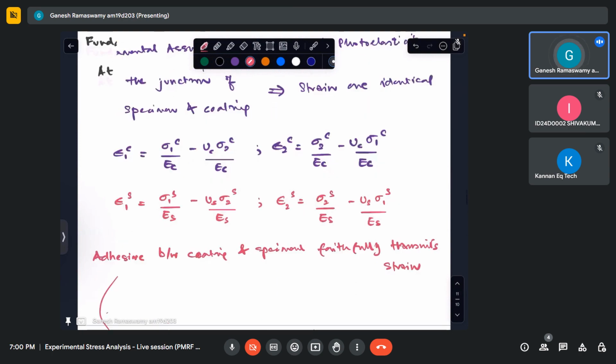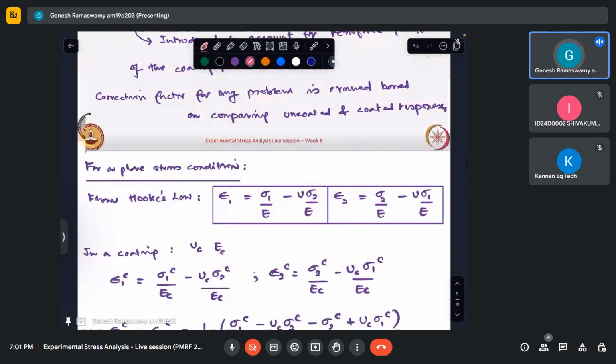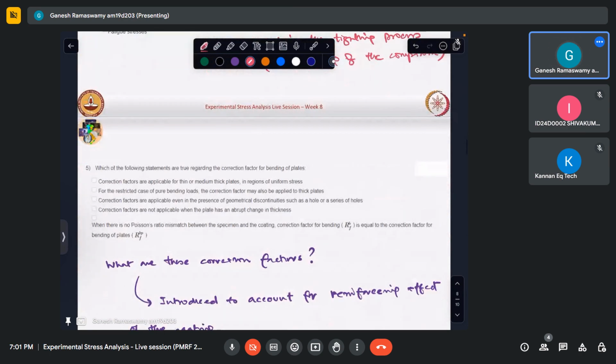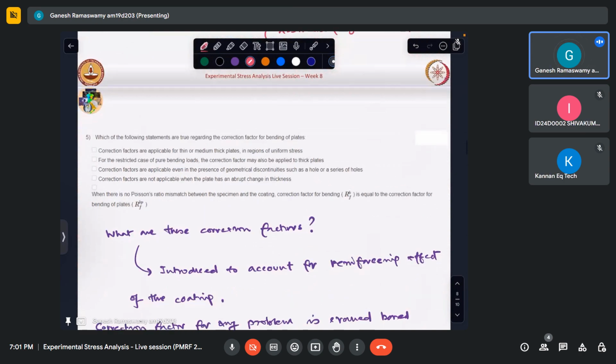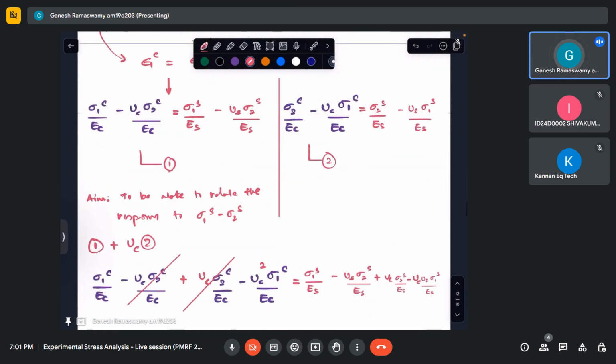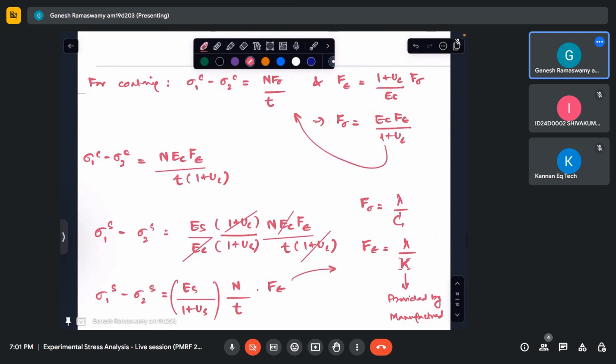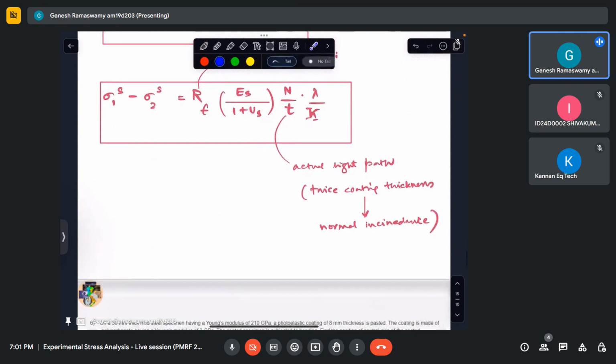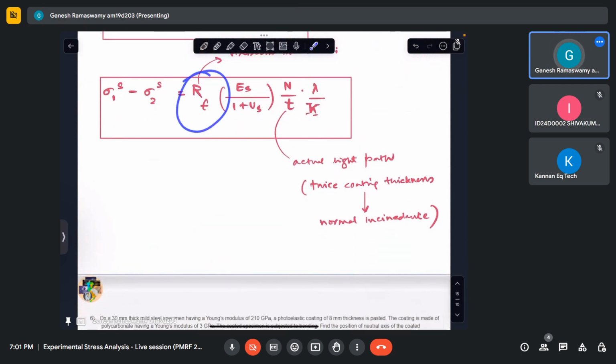If we are trying a uniaxial specimen, first we will analyze what the stress distribution would have been without the coating, and then do the same with the coating participating in load sharing. Essentially, in the lecture, these are published results by Zandman and group. So depending on the problem at hand, we can apply these correction factors.